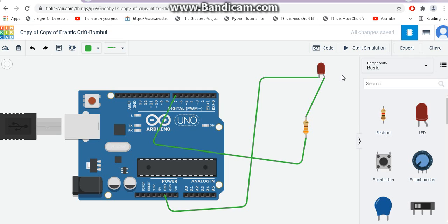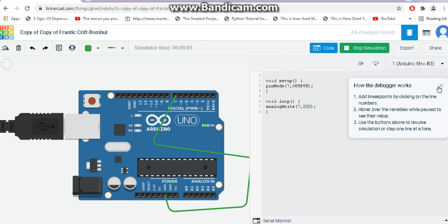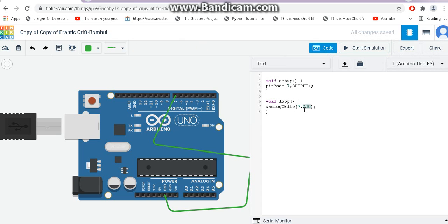Clear brightness change. I'm actually sure there is a brightness change, because I have already done it with a real Arduino. So if you don't find a proper change with this current code, you can go a little lower. You can go for a value of 180, which gives a lower voltage than 3.9. You will understand what 3.9 is if you watched the previous video.